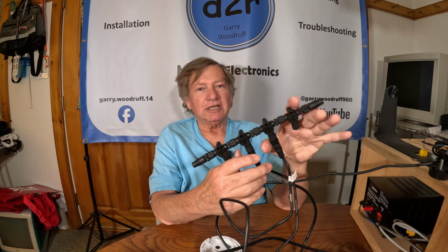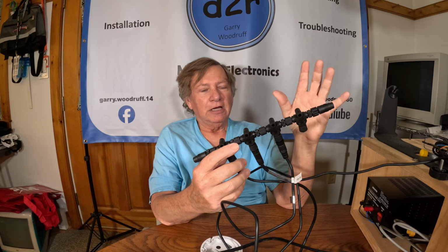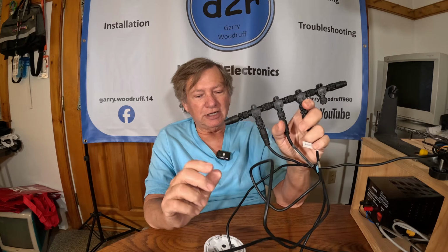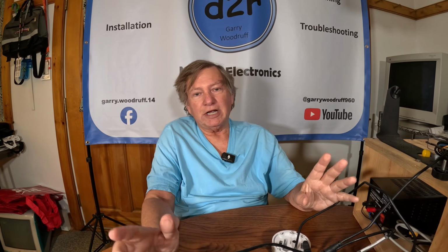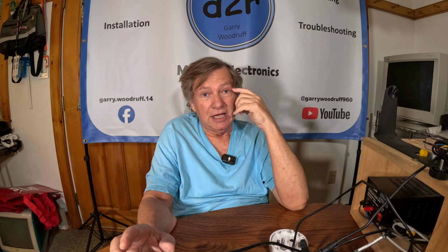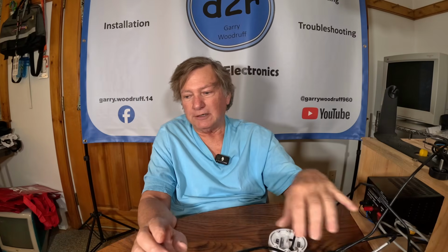Most boats that I've been dealing with, bass boats and the smaller saltwaters under 30 foot, generally can run one NMEA network without having to split power on it. Okay, so that's your NMEA 2000. A lot of times I'll just say NMEA bus. It's NMEA 2000, okay? There is a NMEA 0183, and that's on your power cord. I know you guys have seen that, and everybody asks, what are those extra wires for? It's for the NMEA 0183. Those are older devices, the older iteration of this NMEA 2000 bus, all right?